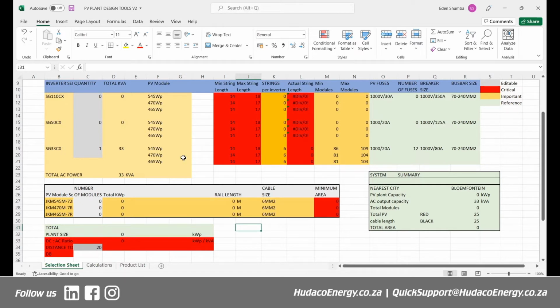All right, so let's say here they said 86, 109, right? But let's put maybe the lowest one, which is 86 panels for the 33CX. What happens? You can see that your DC to AC ratio shoots over the roof. It's actually 1.42 at the minimum. All right? The DC to AC ratio is now very high.